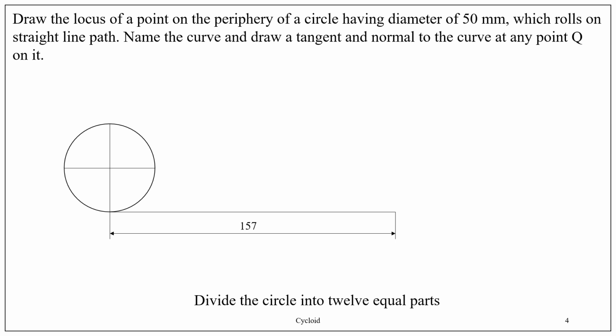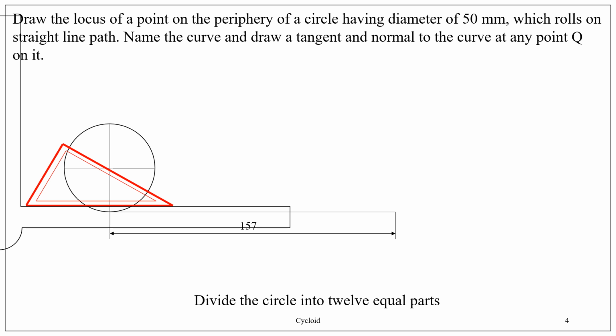What you need to do is keep the longest edge of the 30-60 set square intact with the horizontal scale of the mini drafter and move such that the long edge of the set square is at the center or near the center.